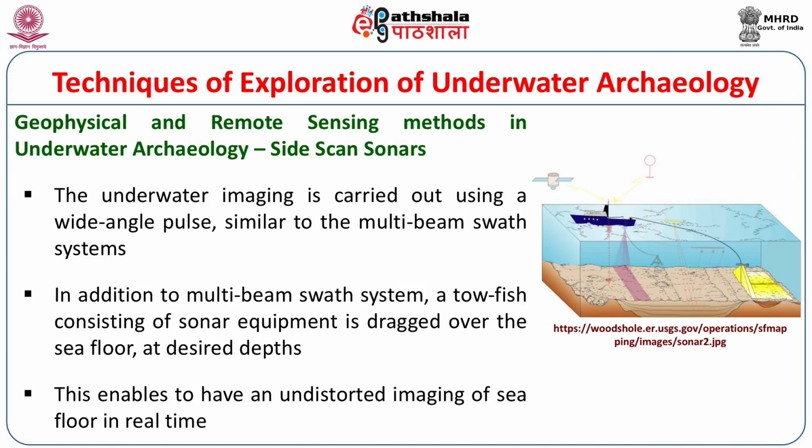This is again an advancement of the acoustic technique, but what happens here is that the underwater imaging is carried out using a wide angle pulse, meaning it is again similar to the multi-beam swath system. But in addition to the multi-beam swath system, a tow fish consisting of sonar equipment is dragged over the sea floor. So this is a combination of two techniques.